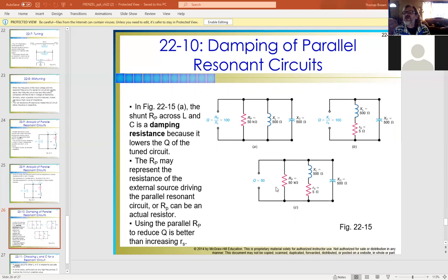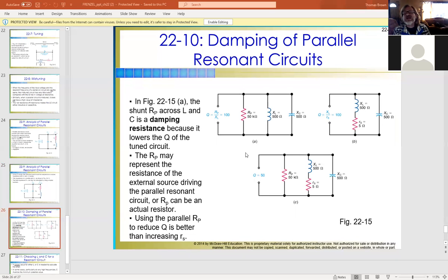With the resistor in there, like he says, it damps the circuit down. Yes, we do end up reducing power by a bit because of the resistor being involved, but the exchange is well worth the reward, right? How much we're giving up in the power end would be how much more we're gaining in overall stability of the circuit, less distortion, attenuation, and whatnot for our signal. And that would be why you would do something like that.